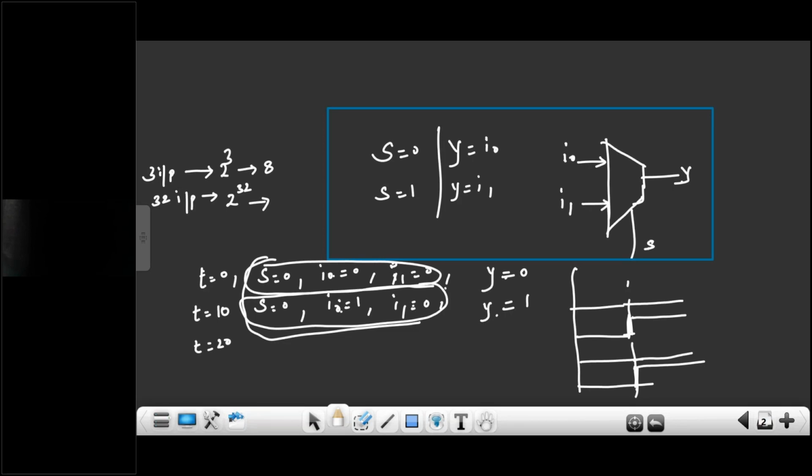Now here comes the intelligence of an engineer. What test cases can I use so that I can cover all the functionality? That is called functional coverage. And what test cases should I use so that I cover all parts of the RTL code, so that all the commands in the RTL code are executed? That is called code coverage.